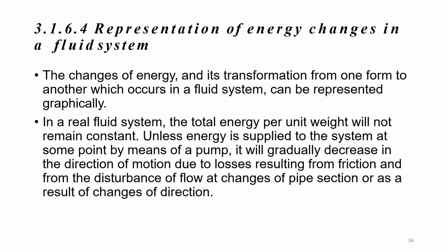Okay, then representations of energy changes in a fluid system. Okay, the changes of energy and its transformation from one form to another can be represented graphically. Okay, in a real fluid system, the total energy per unit weight just now will not remain constant unless energy is supplied to the system at some point by means of a pump.